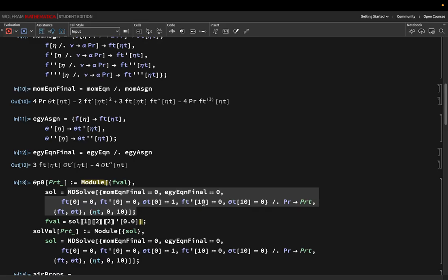The other condition is, when you are writing it mathematically on pen and paper, we say that eta tends to infinity, but we don't actually have to solve till eta equals infinity. We have to give some big number. When we were solving the forced convection boundary layer, if you recollect, the eta value was around 5.6 or something. After that value, f prime was not changing, it was close to 0. In a similar way for this problem, after a bit of trial and error, you will find that when it is close to 10, the value is actually going to 0.